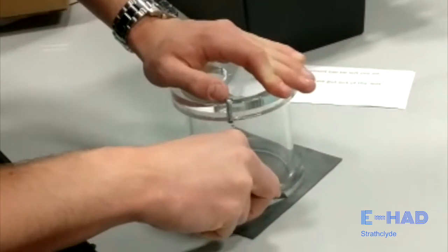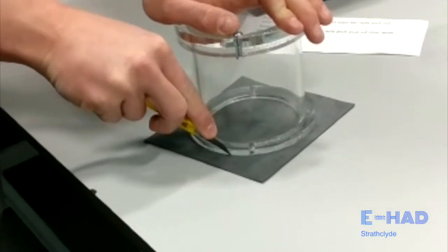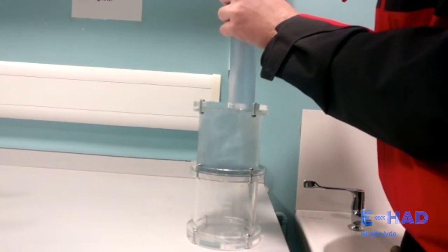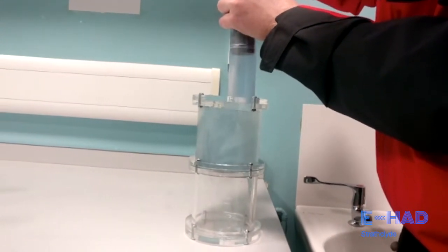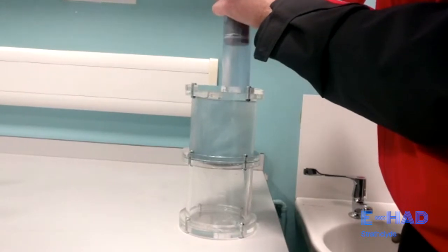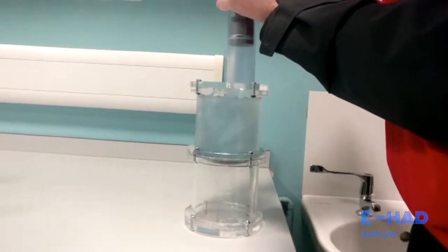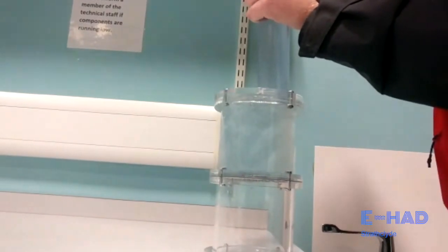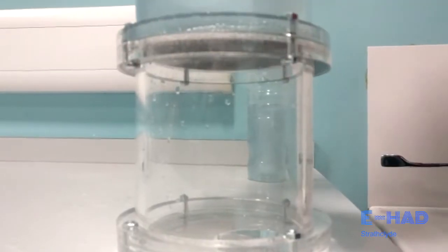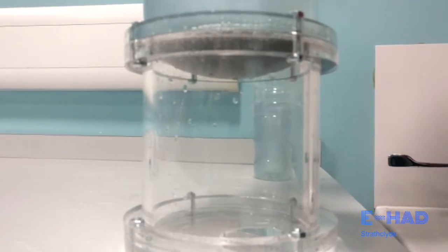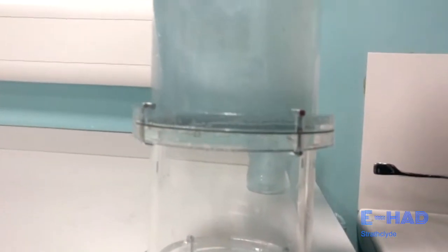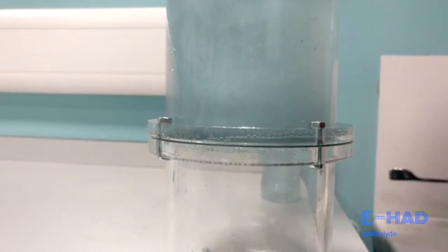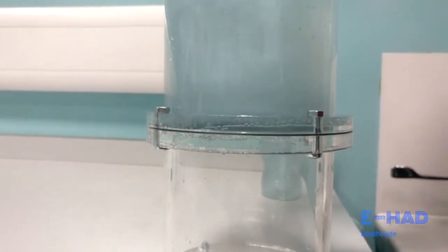The capacitor design consists of two 50mm perspex tubes screwed together through outer flanges with an elastic material between each tube. This material deflects when subject to the water flow, which imitates the capacitor charging up. When the direction of the source is reversed, the water begins to flow in the alternate direction, which allows the elastic to retract back to normal, which pushes water stored within this through the circuit, discharging the capacitor. It's this process of charging and discharging which helps to smooth the AC signal into a DC signal.